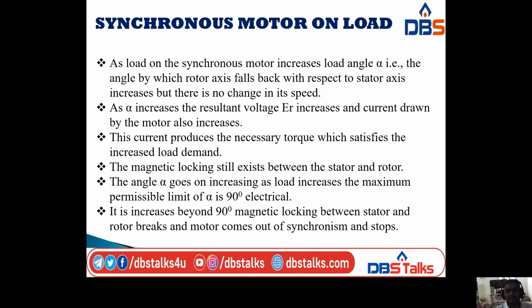As alpha increases, the resultant voltage ER increases, and the current drawn by the motor also increases. This current produces the necessary torque which satisfies the increased load demand on the synchronous motor.